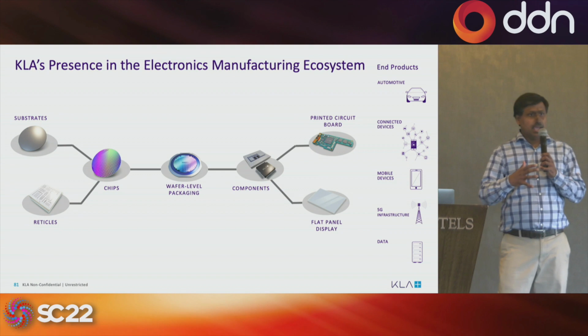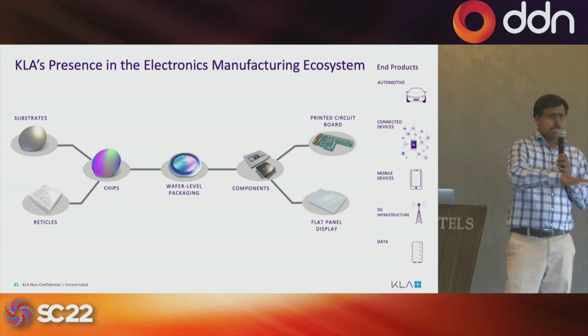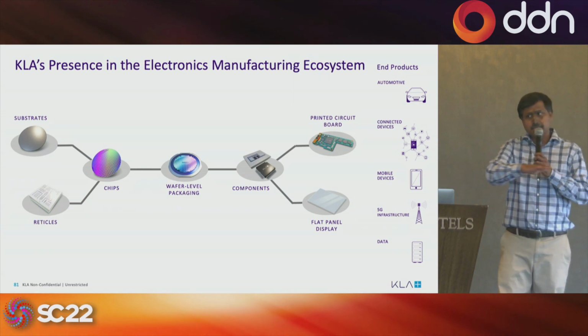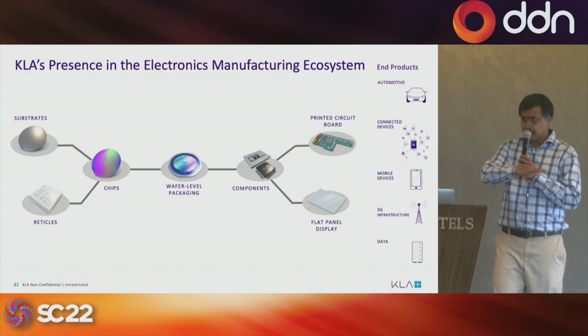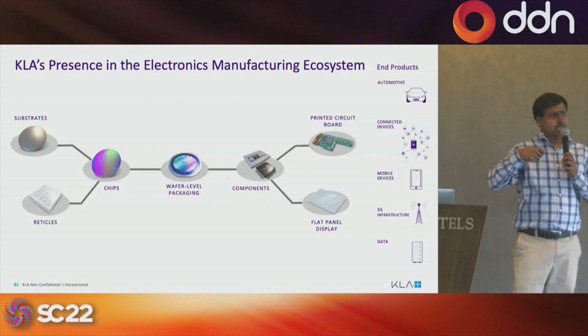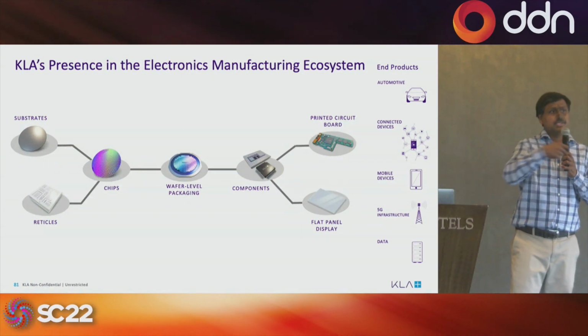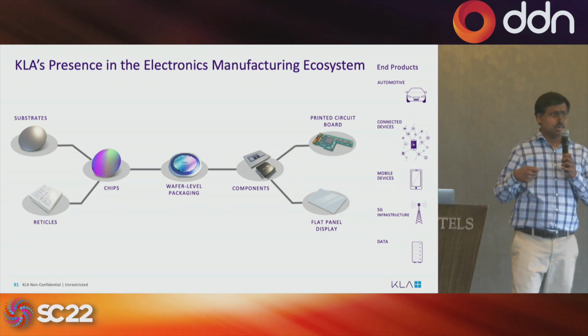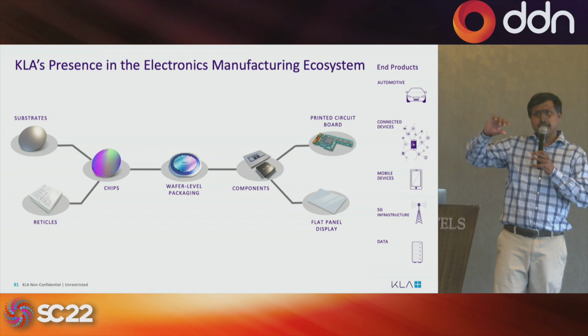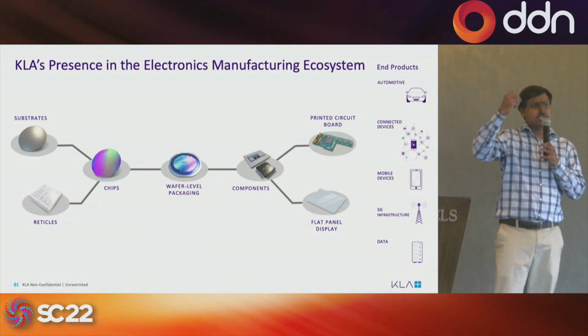As they add a material, they make a new layer. They need to make sure the surface of the material is the way it has to be. And once they etch, they need to see if there are any residues left during the etch process. When they have multiple layers installed, they need to measure the thickness of each of the layers.